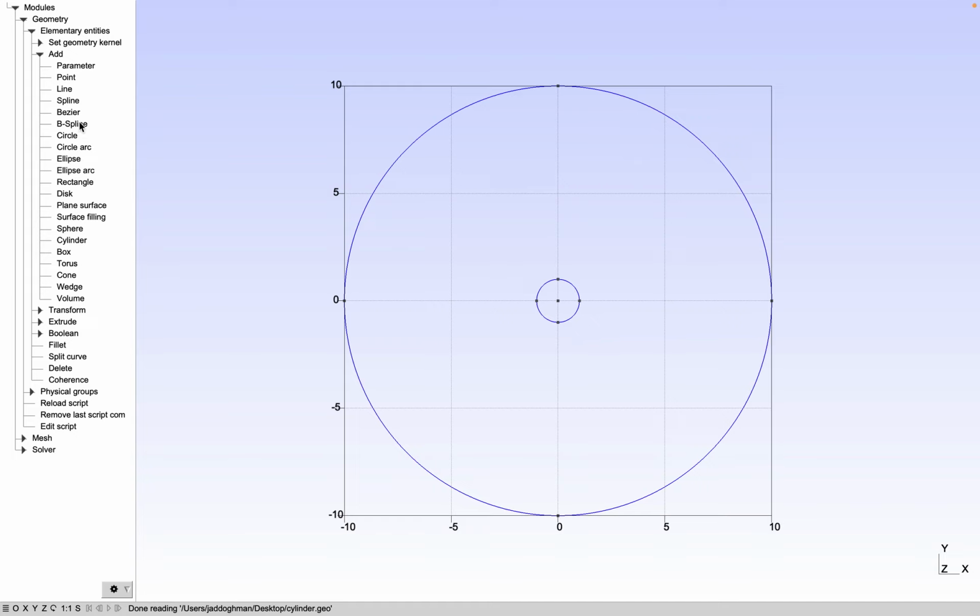To do so, I need to create lines. So I'm going to join those 2 points like that to create the first line. The second line will be done in the same way, similarly here and here. All right, we can press Q to abort.